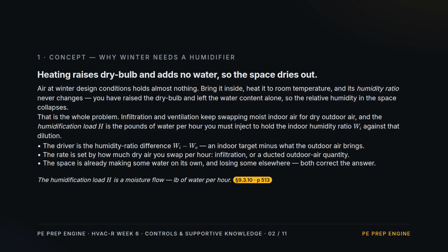Concept: why winter needs a humidifier. Air at winter design conditions holds almost nothing. Bring it inside, heat it to room temperature, and its humidity ratio never changes. You've raised the dry bulb and left the water content alone, so the relative humidity in the space collapses.